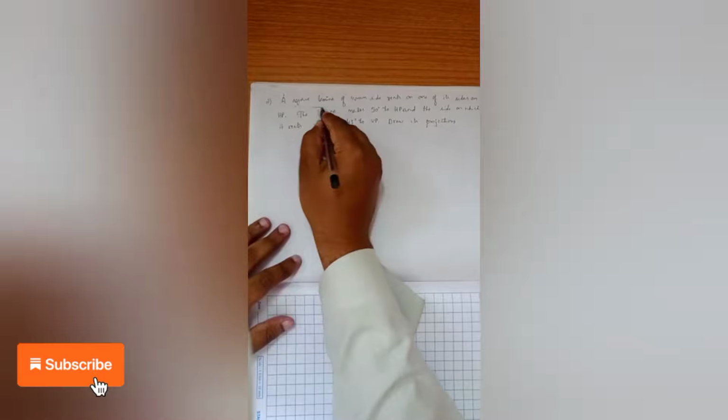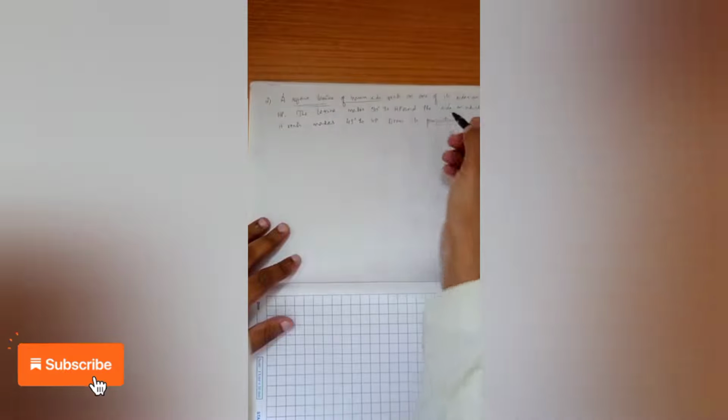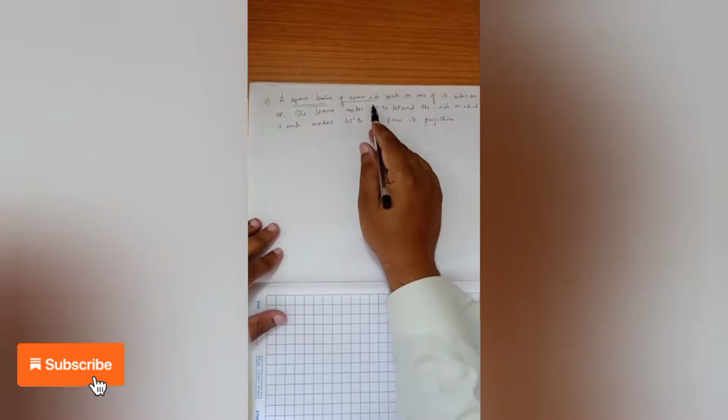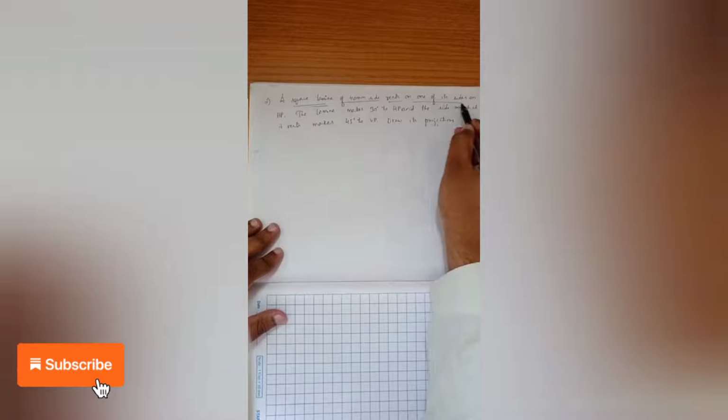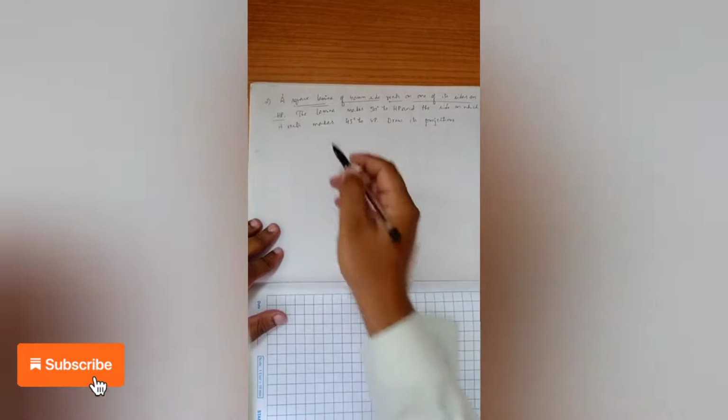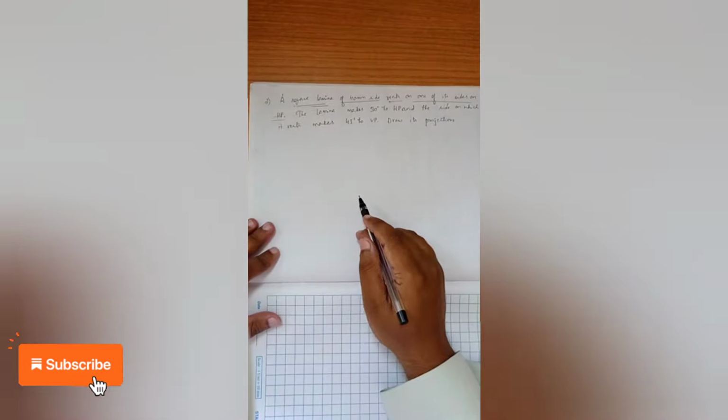Today we are going to learn another normal type of problems in square lamina. So the procedure is the same, that angle of inclination will be there with respect to the edge surfaces. Okay, now see in this problem, it is a square lamina of 40 mm side. We have to construct a square of 40 mm side, resting on one of its sides on HP. So in this problem also your first position starts from the HP plane, and we have to construct with respect to the edge or the side.